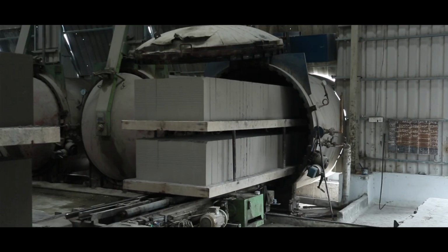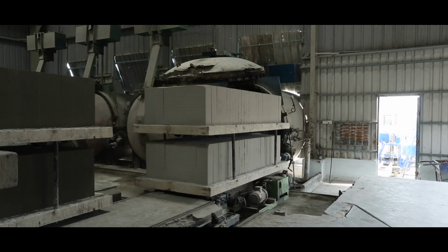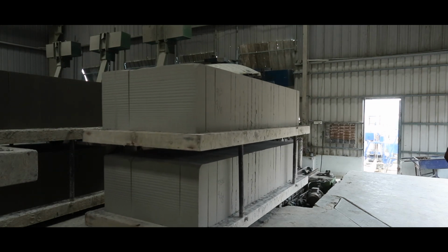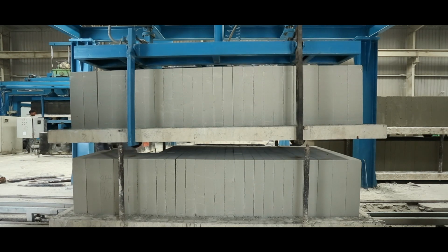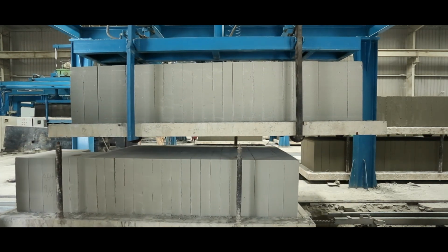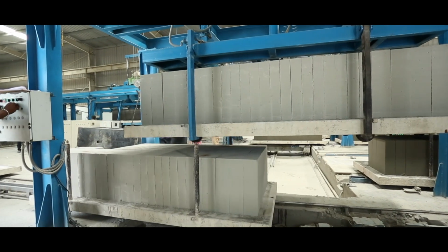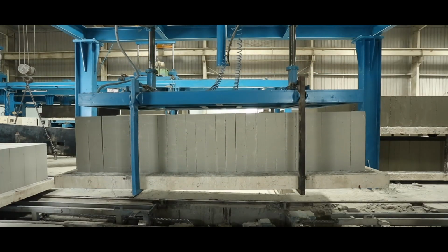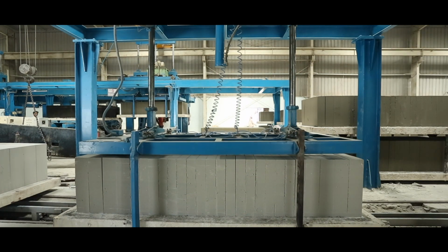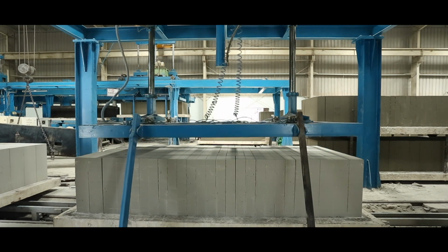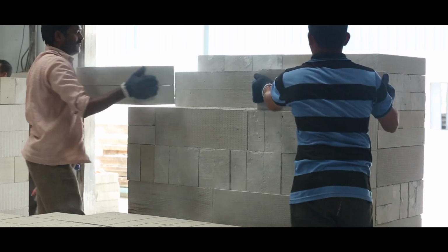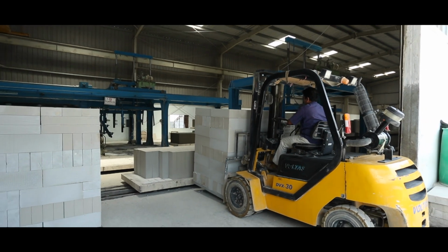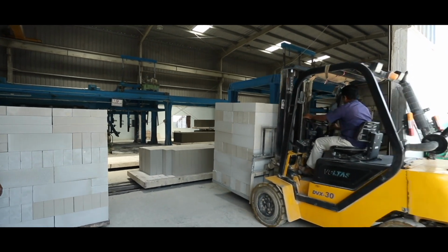After completion of the curing cycle, each doubled up bogie is transferred one by one into the return line. At the single down machine, each cured cake is separated in such a way that every cake is resting on a bogie. The intermediate frames over the cake are then removed. The cured blocks are then carefully removed and systematically arranged. The molds are oiled and cleaned and ready to receive the next pouring batch of slurry.